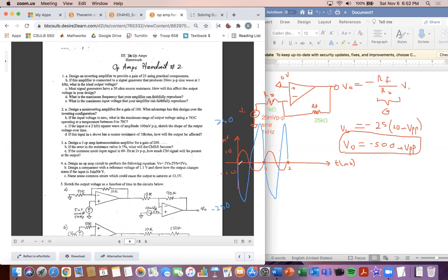This is an inverting amp. Look, it's opposite of the input. It goes up in the input, it goes down for the output. It also amplifies. Look at the gain of 25. It goes from -10 to -250. It goes from 10 to +250 for its peaks.